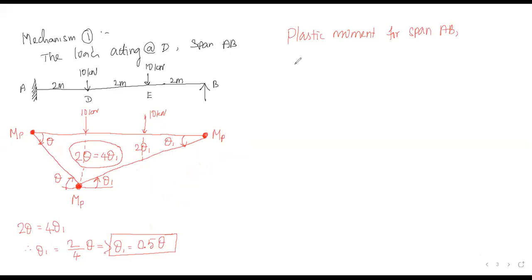As per the virtual work method, we know that internal work done is equal to external work done. Internal work done is because of plastic hinges. So first one, MP theta here.